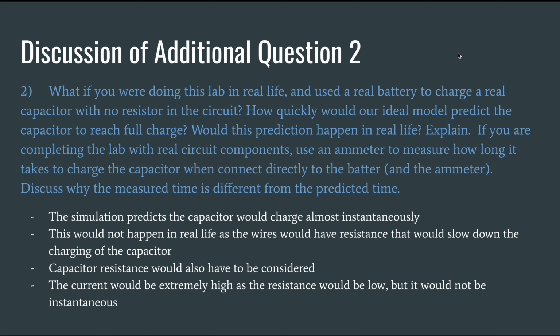And then this one is essentially saying, if you were to use just a battery and a capacitor, what would happen? Well, the simulation predicts the capacitor would charge instantaneously. This would not happen, though, in real life, as the wires do have resistance, the capacitor has some resistance. The current would be extremely high, but it would not be instantaneous charging.